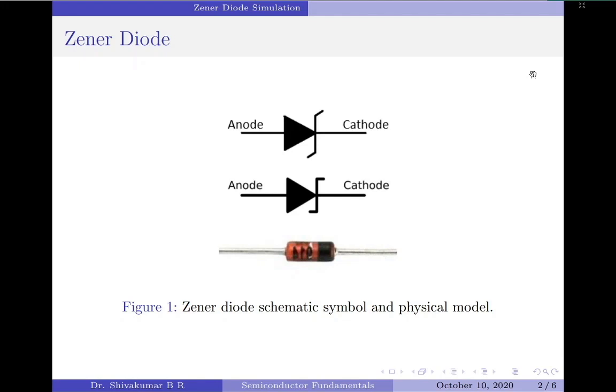That means, in reverse bias condition, Zener diode withstands an applied reverse voltage only up to a certain value called the Zener breakdown voltage, beyond which the diode breaks down due to the Zener breakdown effect. This is different from the avalanche breakdown and occurs at a lesser value than what a normal diode would experience for the avalanche breakdown. That means that theoretically, Zener breakdown occurs at a lower voltage level than the avalanche breakdown in a diode that is especially doped for Zener breakdown.